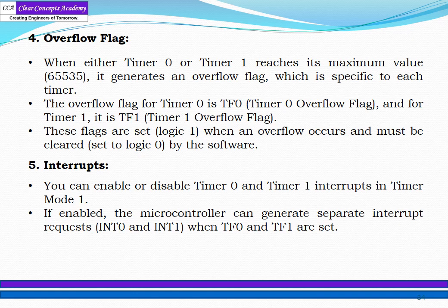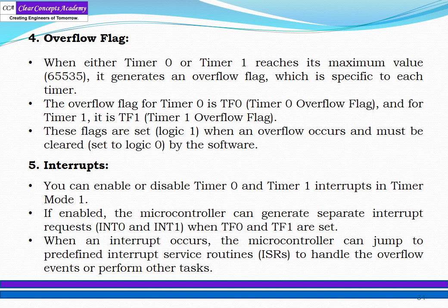If TF0 overflows, INT0 will be activated, and if TF1 overflows, INT1 will be activated. When an interrupt occurs, the microcontroller can jump to the predefined interrupt service routine, ISR, to handle the overflow event or perform other tasks.